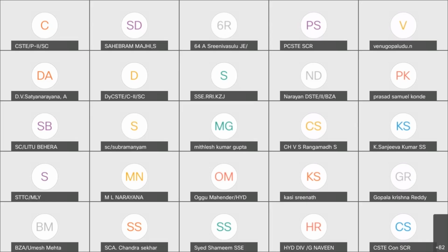One more problem, sir. Only in Sandhu make, there is jamming of the throw bar in its brackets, in the point machine itself. After loosening the bracket fixing, the point will move freely, sir. We are temporarily attending to it by providing a 1.5 mm to 2 mm thickness washer between these two brackets so that it will move freely, sir. During installation and after maintenance, we are unable to find where it is obstructing. This is the main problem, sir. We faced it only in Sandhu make, sir.